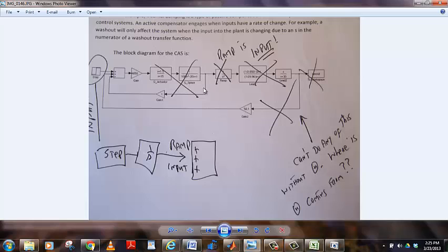If, however, you feed back theta, then you would have to have a theta sensor. And they do have theta sensors. Or, as we mentioned in the aircraft case, you could actually feed back the integral of theta z dot. So if you call that signal q, then the integral of q dt would be available to you as the output of the gyro to feed back as an additional input.